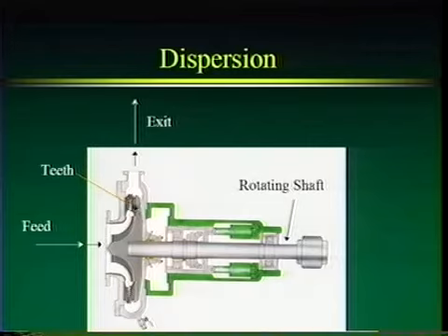It might be hard to see, but the teeth are right here. So this disc is rotating at 1400 RPM, let's say, and the teeth here are moving around and coming very close to the teeth on another disc. The teeth on the other disc are, in this case, stationary. So we have stationary teeth here, and we're getting the teeth to teeth closing the gap. The pulp is trying to squeeze through here. The teeth cut and rub and break contaminants and actually fibers also, unfortunately. And it's just a very quick action. 2 seconds in here, bang, and then the pulp leaves out the exit.